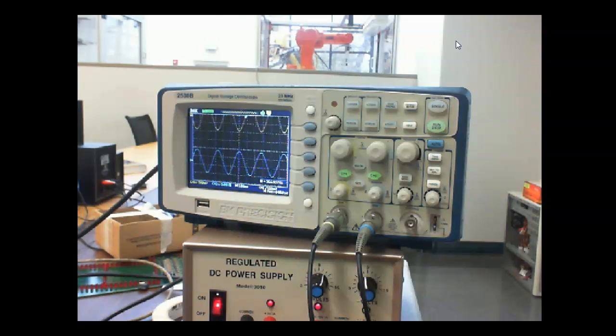If you have a coax wire break, you just can't strip them and twist them back together. If one of these network cables breaks, you just can't twist them back together, right? If you've ever made network cables, when you crimp them, you have to maintain that twist as far as you possibly can. You just can't twist wires together, because you screw up your impedance matching.